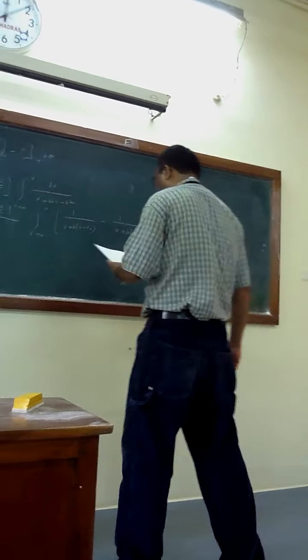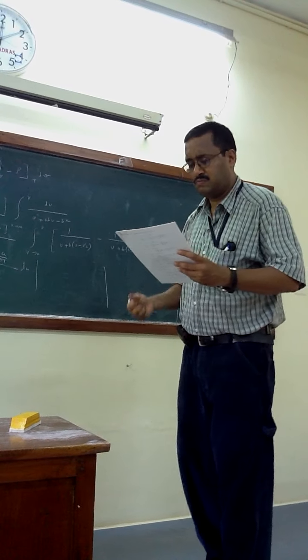Next step. I think you have done it. So what I would expect is A(T) minus T dou A by dou T divided by 2 root 2 B, ln, which will give me in terms of Z, Z plus capital B into 1 minus root 2 by Z plus capital B into 1 plus root 2.